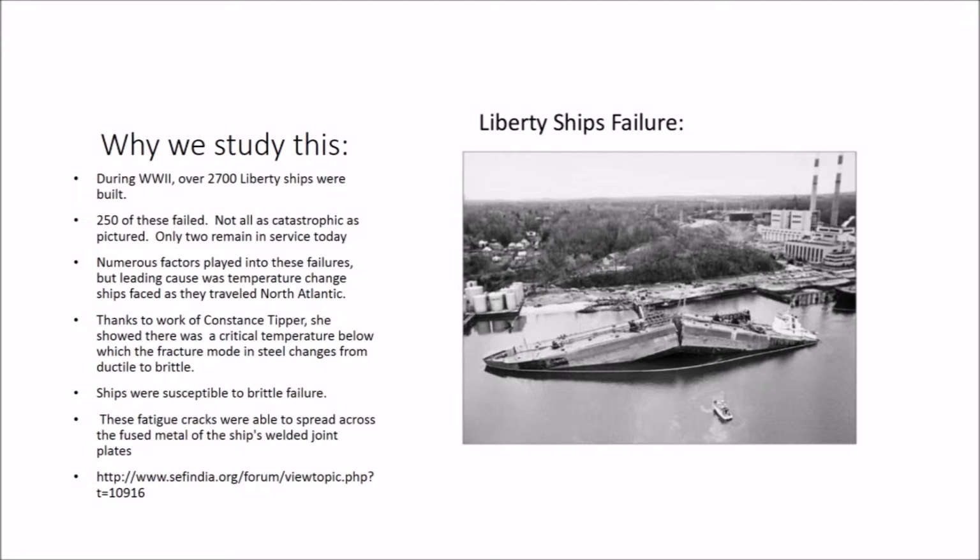The fatigue cracks were able to spread rapidly across the fused metal of the ship's welded joint plates, and instead of being stopped at the plate edge of a riveted joint, they continued on, causing the catastrophic failure.